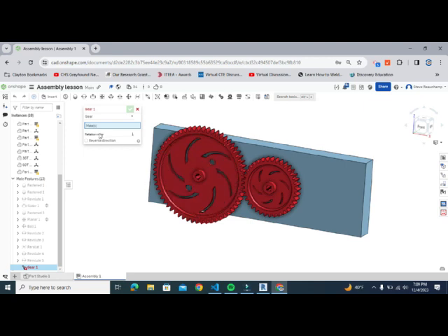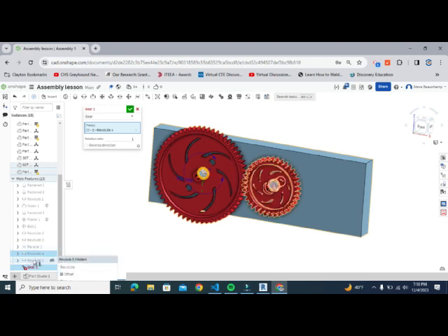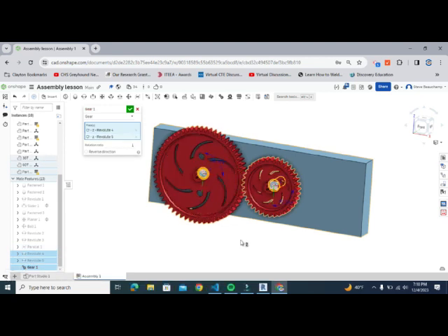out over in. Okay, so the mates, it wants to know this time not the parts, but what mates do we want to connect together. Well, that's going to be revolute 4, and then it's going to be revolute 5. So those two mates, when we drive one, it's going to drive the other. And then we've got this relation ratio, and that's our gear ratio. So if this is a 36-tooth gear, it's going to be 36 divided by 60. So it's the number of teeth out over the number of teeth in. We'll hit check.